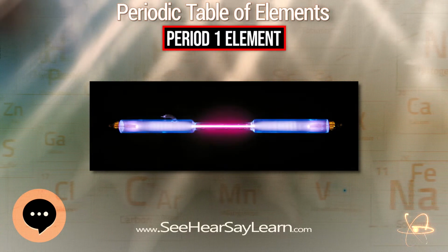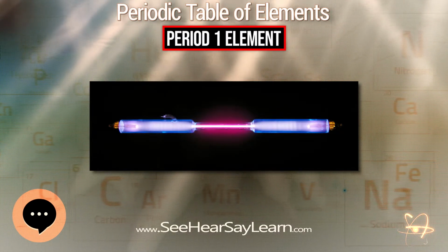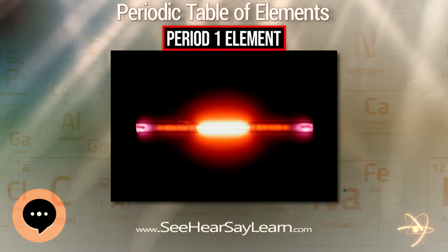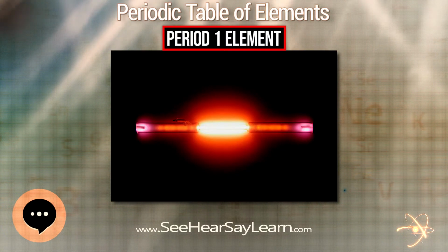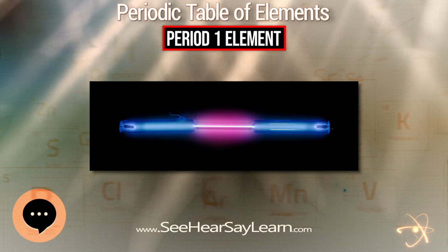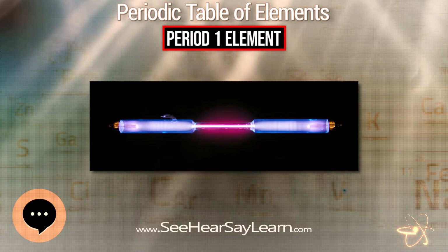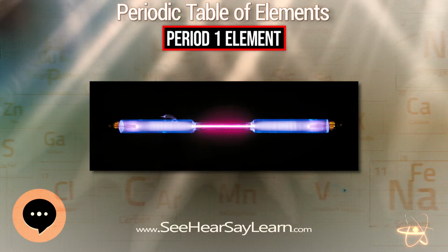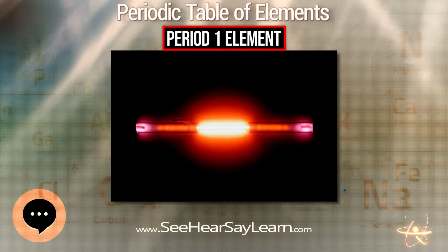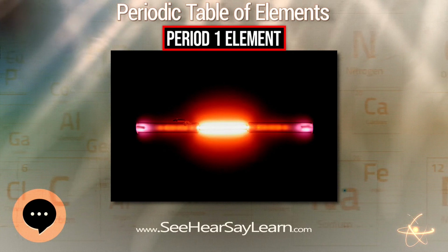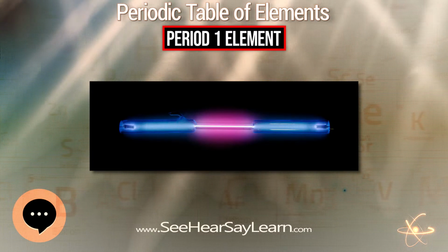The interactions of hydrogen with various metals are very important in metallurgy, as many metals can suffer hydrogen embrittlement, and in developing safe ways to store it for use as a fuel. Hydrogen is highly soluble in many compounds composed of rare earth metals and transition metals and can be dissolved in both crystalline and amorphous metals. Hydrogen solubility in metals is influenced by local distortions or impurities in the metal crystal lattice.